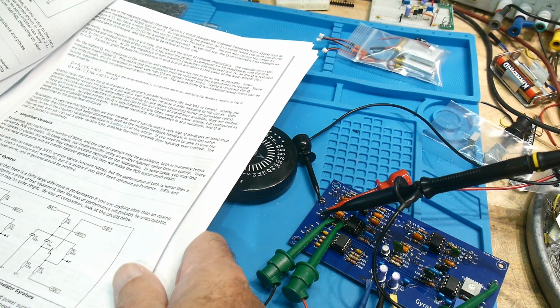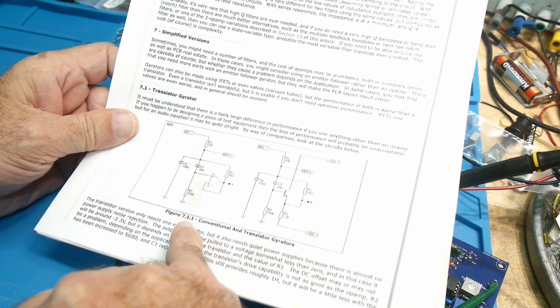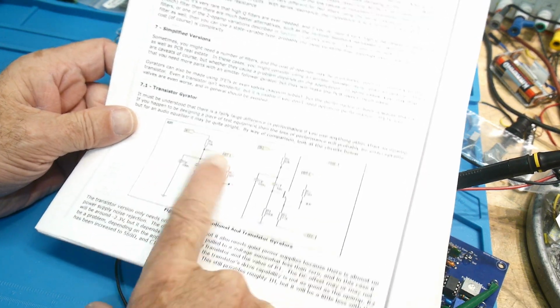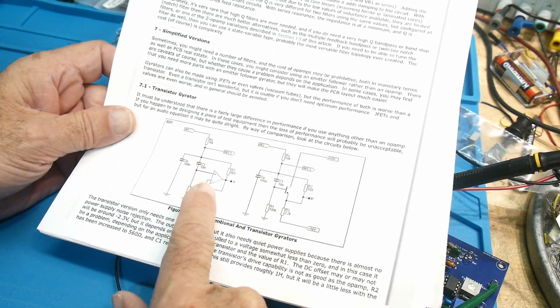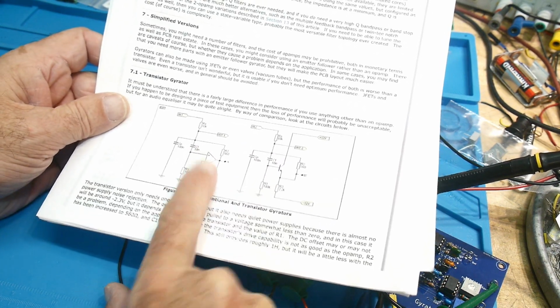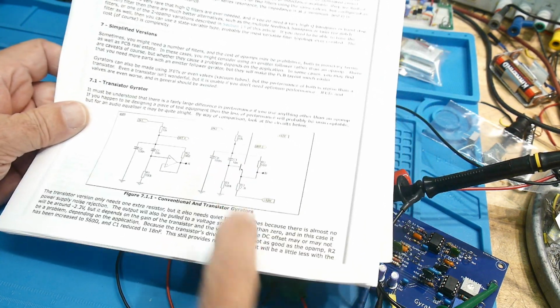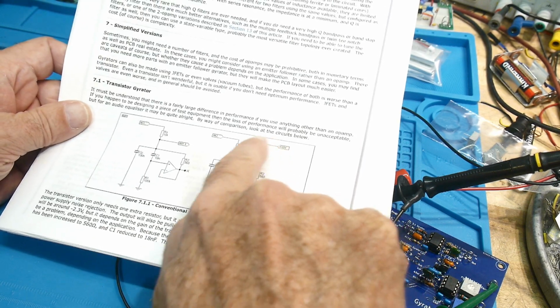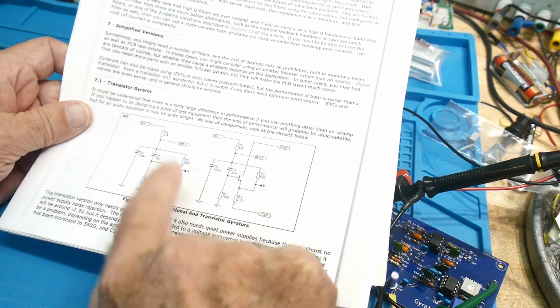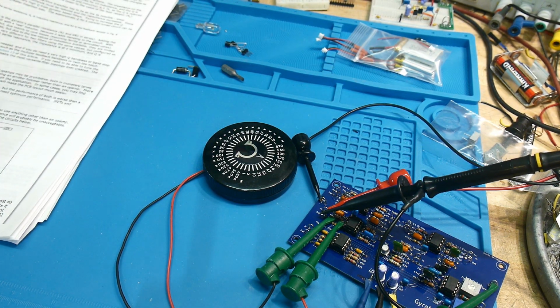All right, let's go to our next circuit, which is going to be this one down here, 7.1.1. We're going to have a circuit that's made up of an op amp, and then we're going to have a circuit that's made up of basically an emitter follower. So this is just a unity gain buffer, and we're going to use an emitter follower as a unity gain buffer, okay? Be a little bit aware of this circuit here. It has the plus voltage. It also has a minus voltage running it. So just like the op amp has plus and minus voltages, this has plus and minus voltages on it. All right, so let's try those two.